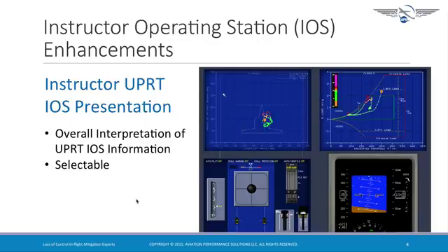We can see this summarized here by the alpha, beta, angle of attack versus side slip, V-N diagram, control positioning, which includes not only the side stick in this particular case, but also thrust position, flap configuration, speed brake use, and trimming, and very often autopilot modes across the top that we can see here. And this is a repeat of what the pilots are looking at in the cockpit. We are going to get into more details on this as we go through the program.